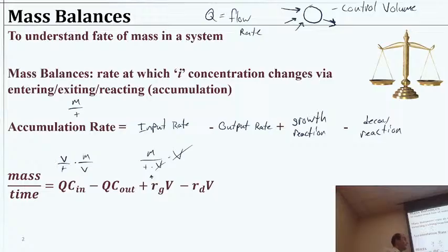Okay, it doesn't really matter how we're dealing with this. We could even say, I am scooping 1 kilogram of calcium chloride into the reactor every minute. That's a mass per time addition. It's already in mass per time units, so I don't need a volume. I don't need a flow rate. I don't need any of that. It's a mass per time addition.